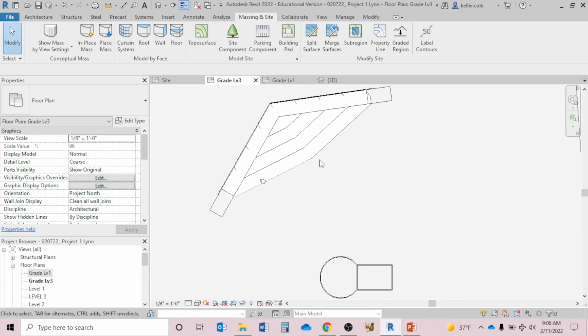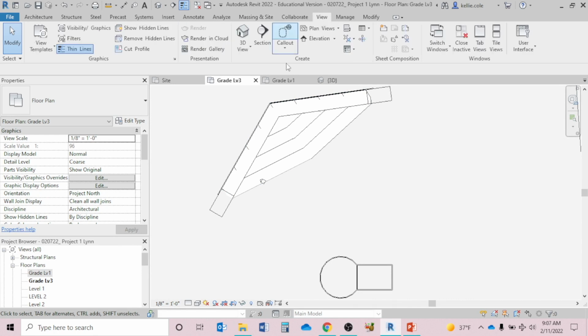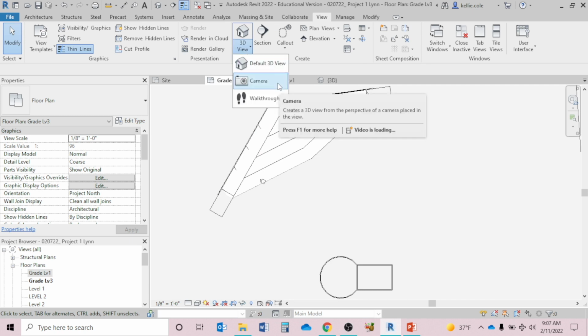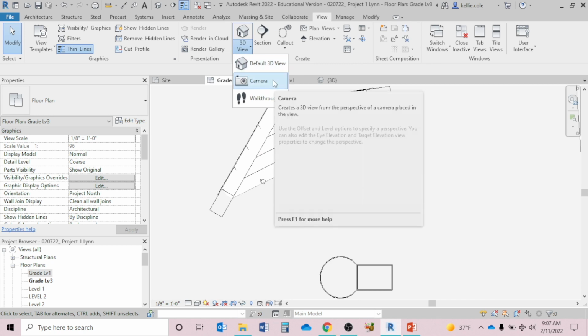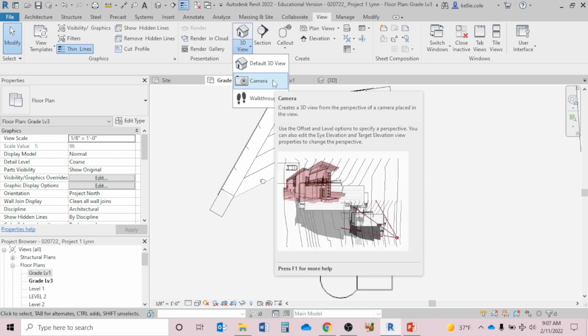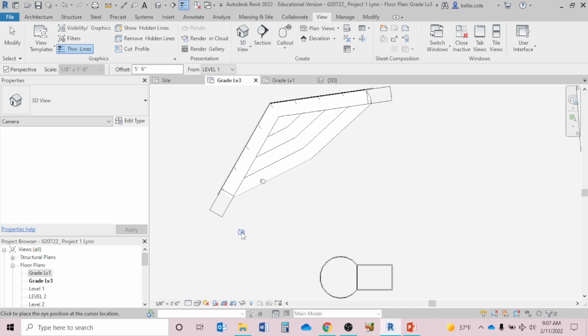And I want you to go up to the View tab. In the middle of the ribbon, there is the 3D view that we'll click, and we're going to click on the drop-down button at the bottom of that ribbon button for a 3D view and hit Camera. When I touch Camera, I see I have a small view camera in my drawing.